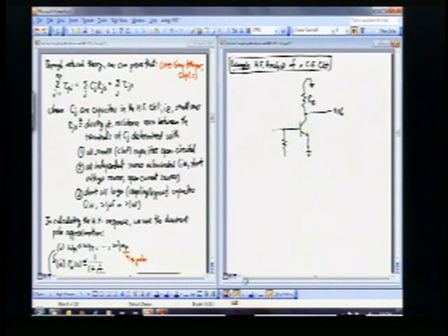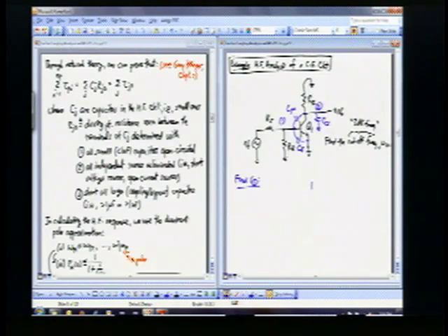I'm going to go ahead and, to be very explicit, just redraw this circuit here. So there's your RC. There's your Q1. And I have two resistors coming out in this direction. So I have an RB here and RS. So again, using this methodology here, all small, less than 1 nanofarad capacitors are open circuited. And so I have open circuited CCS. I have open circuited C-pi.